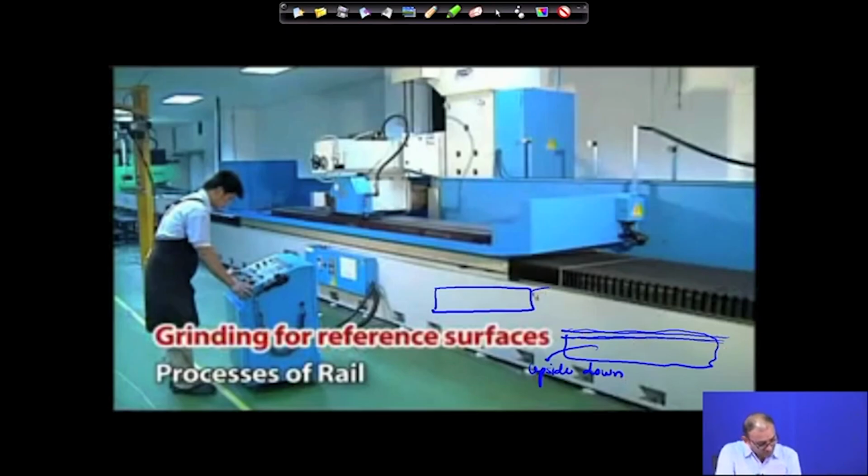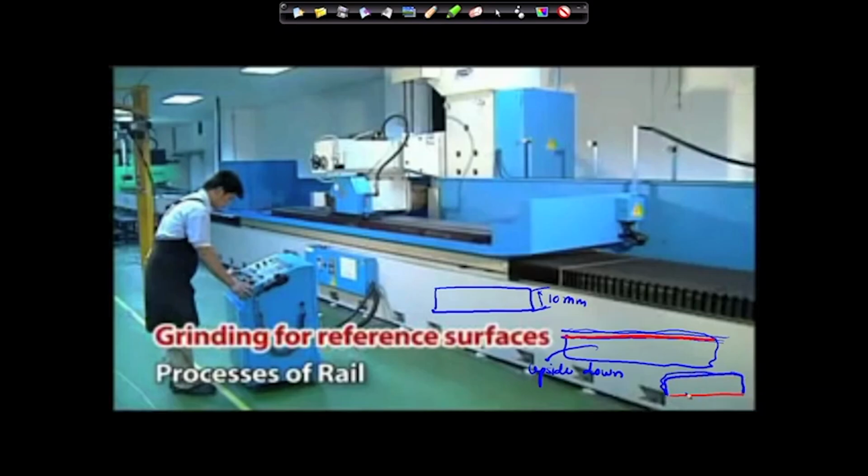So, now we have created this reference surface. All the dimensions you want to machine, suppose it is 10 millimeter, will be measured from that location. So, now this is your reference surface, and you have reached this location. Now, mount it upside down. Your surface is something like this. The top surface may again be very uneven, but your bottom surface is completely flat, because you have taken it as the reference surface.